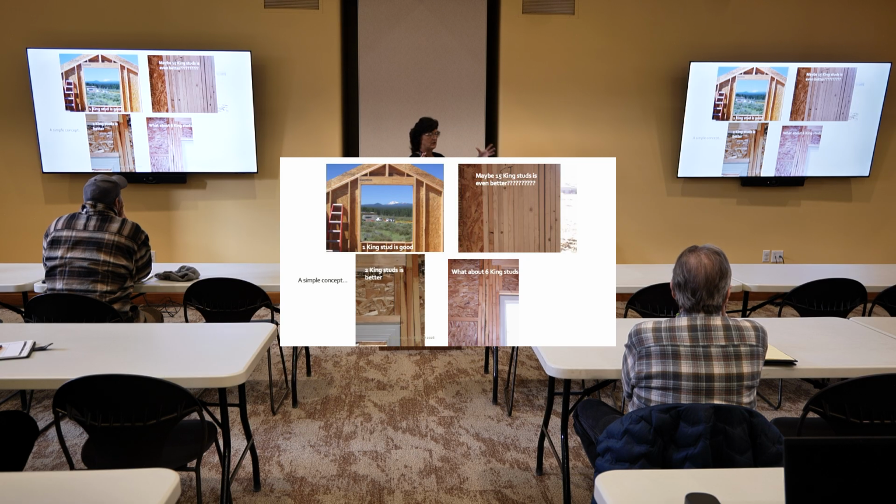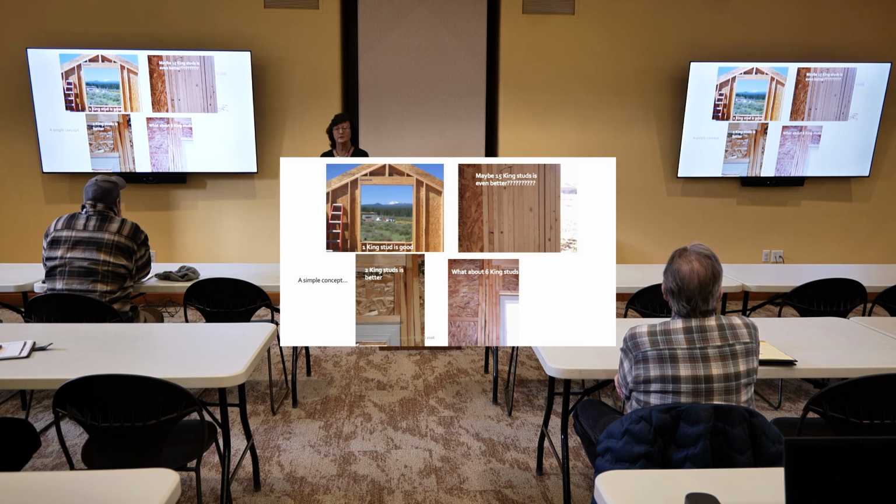But you get stud packs, you get all kinds of things that are now causing these big, huge thermal bridges, right? They might be great structurally, not 100% sure they're needed, but they might give you peace of mind, I guess, structurally. But just pay attention to the 2021 and the 2024 IRC, because the home builders, really the National Association of Home Builders, did a huge effort of going in there and stripping out a lot of the excess framing that was in there. And so you don't need triple headers in a lot of places. They got some of that removed.